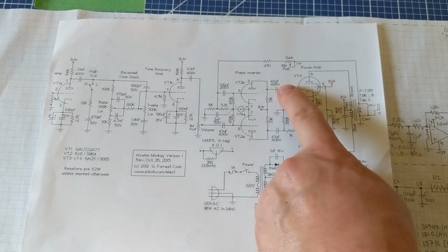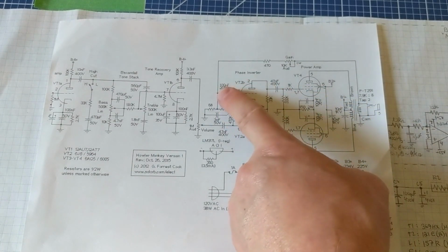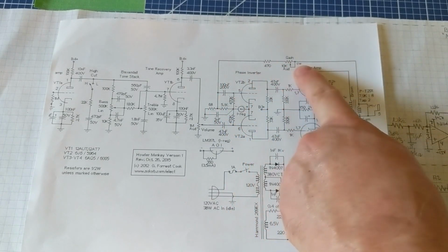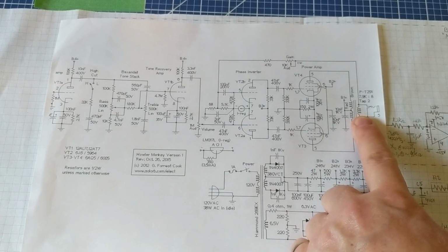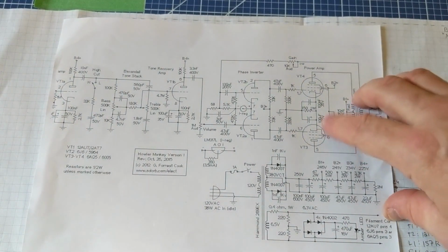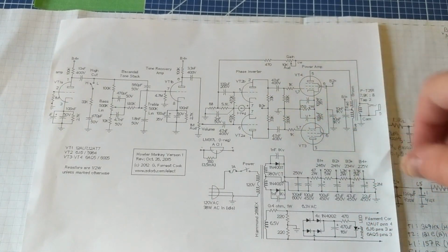The other phase is on the top here, and its input is for the most part grounded, although he did use it as the feedback path from the output amp to reduce some of the open loop gain. This is something I'll explore later on in my design. From that, I can get some idea of what values of resistors and capacitors he was using in his design.